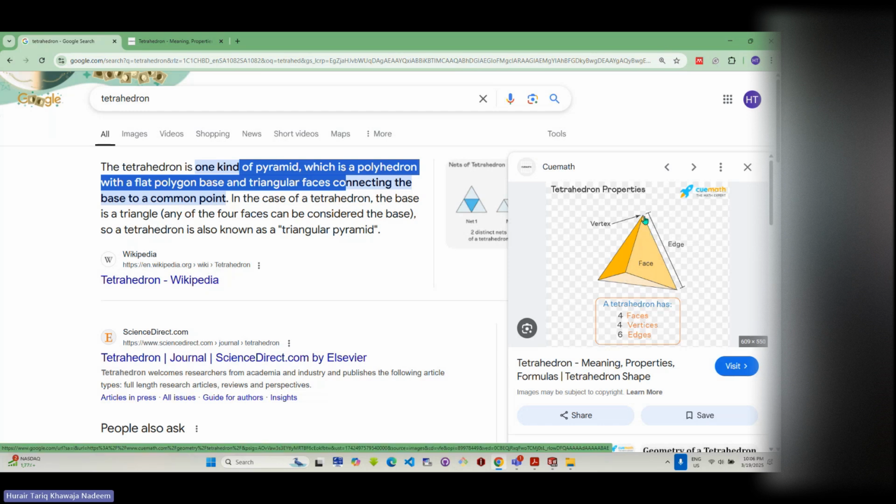So how many nodes? Nodes are actually the corner points. Remember this thing. And each node has got certain degrees of freedom. Degrees of freedom tells you in how many directions each node can move. Nodes actually talk to each other. So the nodes of an element talk to the nodes of another element. Remember this thing. This is the theory of finite element. You will study it afterwards. We are not going to go into detail, but you write the equations of the nodes.